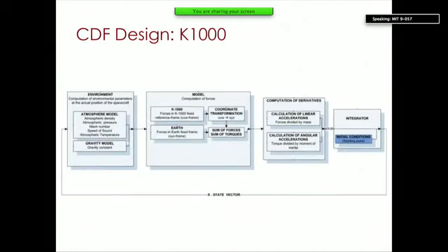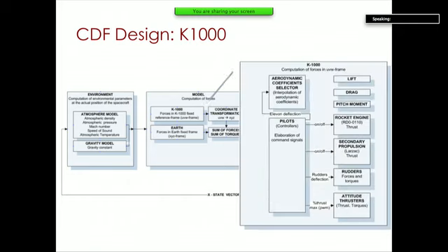Okay, so once you know your requirements, you can really start developing your models. So here's a model of essentially the kinematics of the vehicle. You have your environment: your atmospheric model, atmospheric density, pressure, Mach number, speed of sound, a gravity model, then computing the forces and torques acting on the vehicle itself, looking at the derivatives, integrating that. This is essentially the equations of motion of the vehicle in the environment it's operating in, and then updating that with a certain time step, delta t.